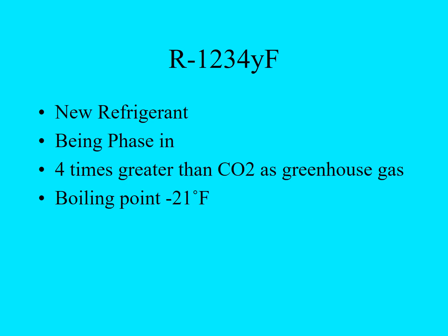So this is the new refrigerant that's being used. This is R1234YF, okay, and it's being phased in. Not all manufacturers have started using this, but quite a few vehicles have it now. And the big selling point here is two things. One, it's only 4 times greater than CO2 as a greenhouse gas.